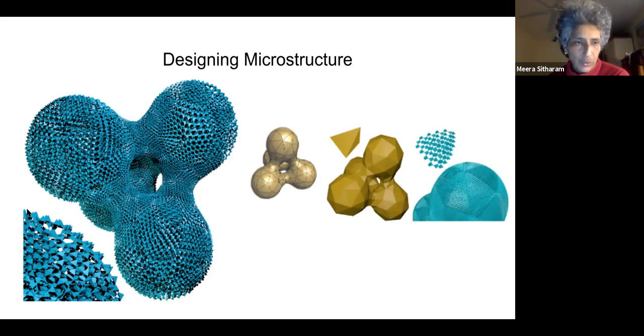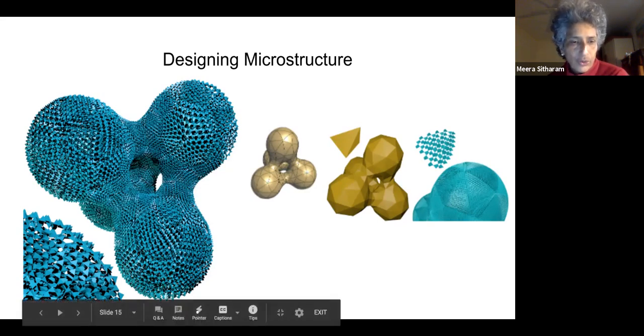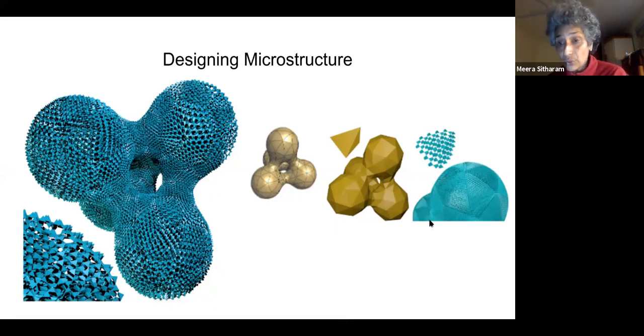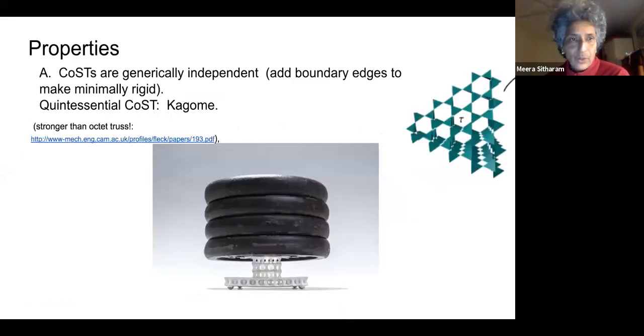What is not shown here is what we call boundary stiffening. If we don't stiffen the boundary, as you can see, if it's all free here, the whole thing will just collapse. We're thinking of these as pin-jointed, in other words the usual bar-joint structures, which doesn't change whether you have bars at the 6 edges of the tetrahedra or a solid tetrahedron. It's the same thing. And you can refine and add irregularities and all this other fun stuff, and I'm going to get to that.